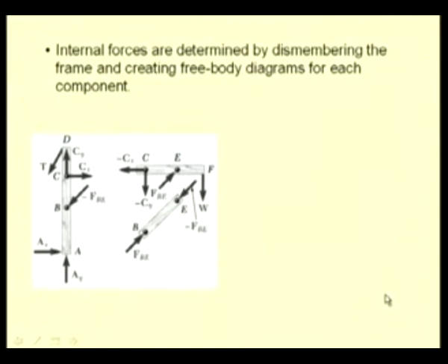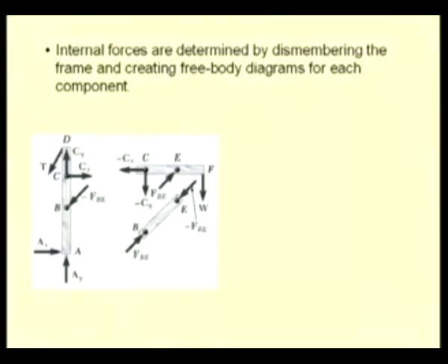Now, in order to analyze the forces that act at various points of these interconnected bodies, we have to dismember and construct the free body diagram of each of the constituent members, both multi-force as well as two-force members, and solve the resulting equilibrium equations. So, here for this example, these are the free body diagrams of the constituent members.